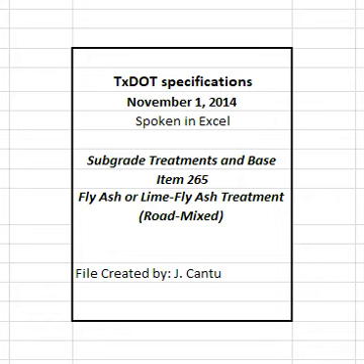Reimburse the department for subsequent mix designs or partial designs necessitated by changes in the material or requests by the contractor. Limit the amount of recycled asphalt pavement to no more than 50% of the mix unless otherwise shown on the plans or directed. 3. Equipment. Provide machinery, tools, and equipment necessary for proper execution of the work. Provide rollers in accordance with Item 210, rolling. Provide proof rollers in accordance with Item 216, proof rolling, when directed.